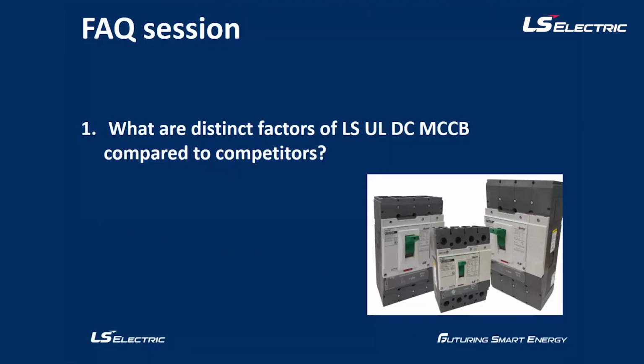Besides, the short circuit breaking capacity will be 65 kA for the whole range. In the case of the UTD 250, 250 amps per breaker, we are right now offering not only a smaller dimension than one of the biggest manufacturers in Europe, but also world-best tripping performance, 65 kA at the same time, with user-friendly accessories installed inside and outside of the breaker. The device can be operated remotely as well, so that you can control this system remotely. So that is the end of the answer.